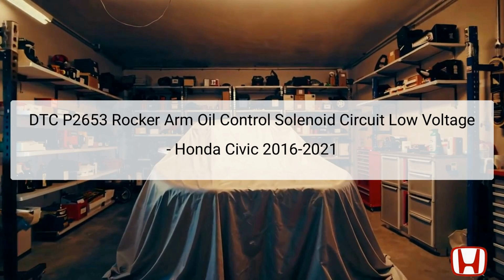The diagnostic trouble code, DTC P2653, is related to the rocker arm oil control solenoid in the Honda Civic from 2016 to 2021. This error occurs when the circuit indicates a low voltage, preventing the solenoid from functioning correctly. The rocker arm oil control solenoid is responsible for adjusting the oil flow to the rocker arms, which in turn manages the variable valve timing, optimizing engine performance and efficiency.